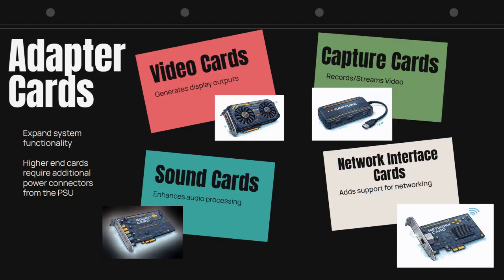Now, adapter cards. Adapter cards expand system functionality. Video cards generate display output, capture cards record or stream video, sound cards enhance audio processing, and network interface cards support wired, wireless, or fiber networking. High-end cards may require additional power connectors from the PSU.